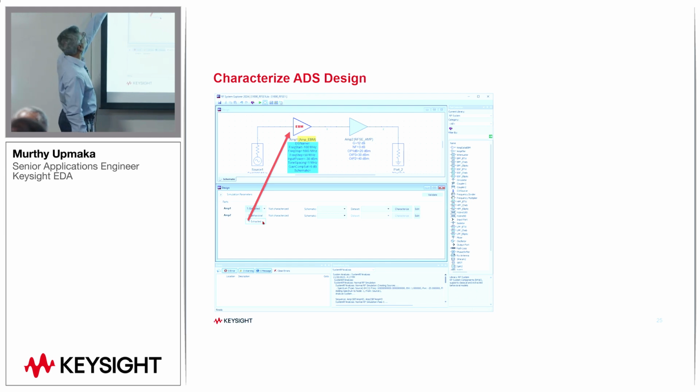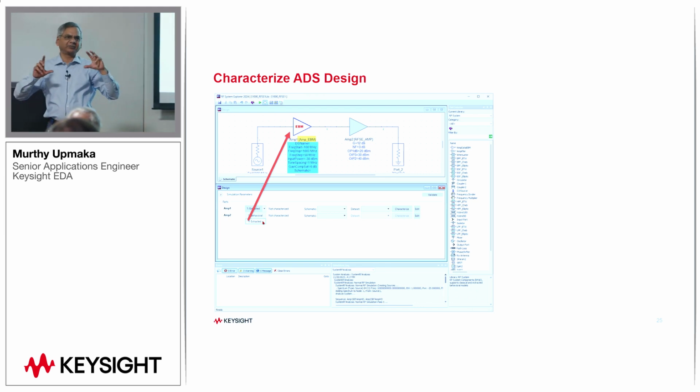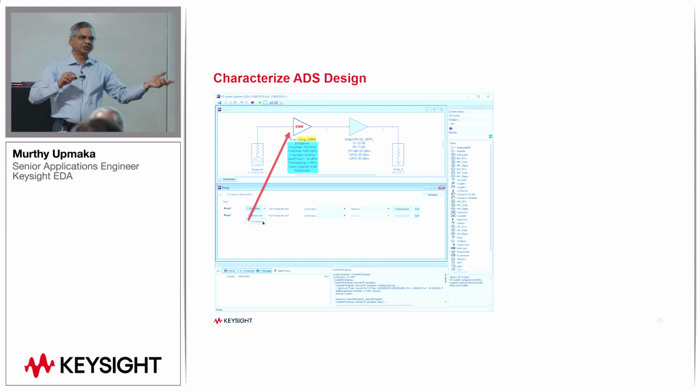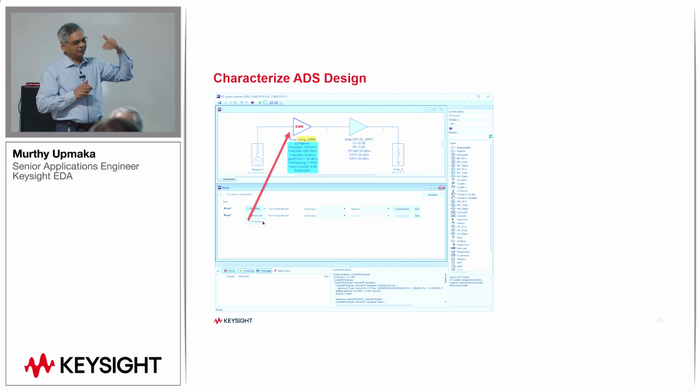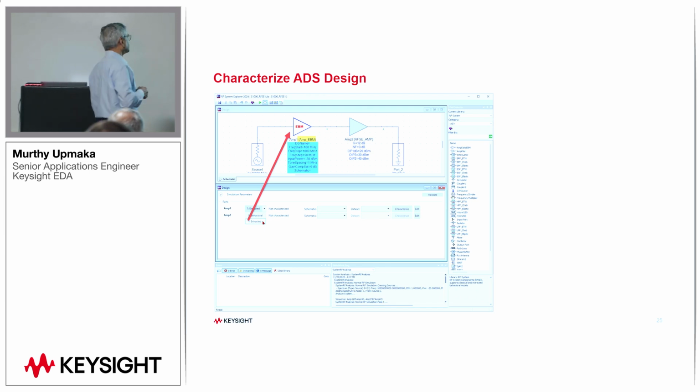You see that on the menu? Yeah, I see it. When you push that, it will do the RF lineup analysis, the one that I have shown previously. What you're doing is you're asking the tool to extract a good behavioral model for your circuit and put it into the system context, and then run the system analysis there for you to be able to see the outputs.